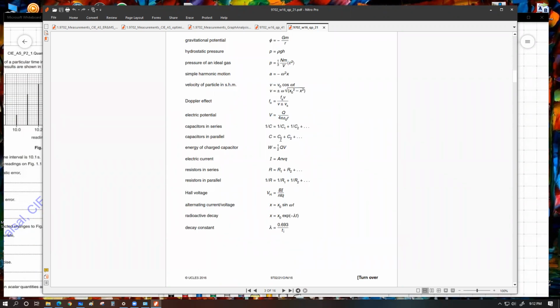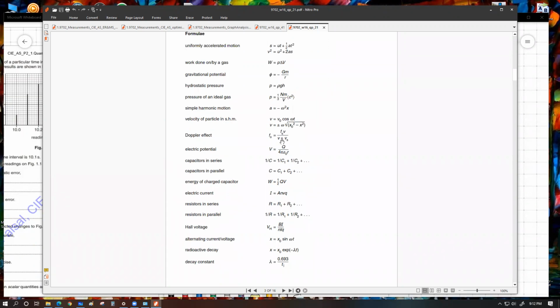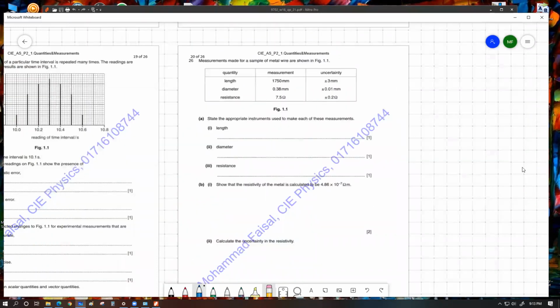এইখানে অ্যাকচুয়ালি resistivity equation দেওয়া নাই, আমি তোমাদের লিখে দিয়েছি। সমস্যা নাই, resistivity equation হচ্ছে R equals ρL over A, এই ρ হচ্ছে resistivity। This equation actually comes from two proportionalities. We know that resistance of a certain conductor is directly proportional to its length. Resistance of a certain conductor is inversely proportional to the cross-sectional area of the conductor, so 1 upon A. If you combine these two, you're gonna end up with R is proportional to L over A.